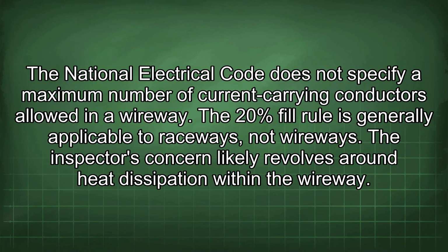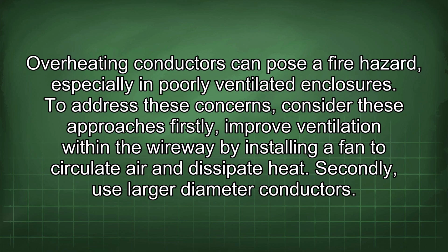The National Electrical Code does not specify a maximum number of current-carrying conductors allowed in a wireway. The 20% fill rule is generally applicable to raceways, not wireways. The inspector's concern likely revolves around heat dissipation within the wireway. Overheating conductors can pose a fire hazard, especially in poorly ventilated enclosures.